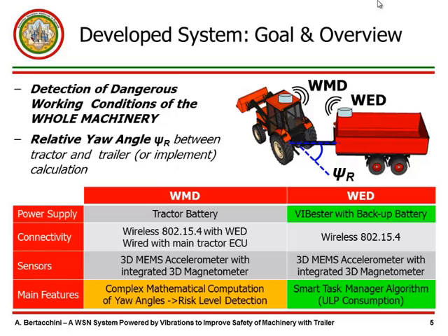The power consumption constraints are very strict in this kind of application. Therefore, the classical ultra-low power design techniques for the hardware components are not enough, and there is a need of a more complex approach, in particular a hardware-software co-design approach. And for this reason, we also implemented a smart task manager algorithm running on the device.